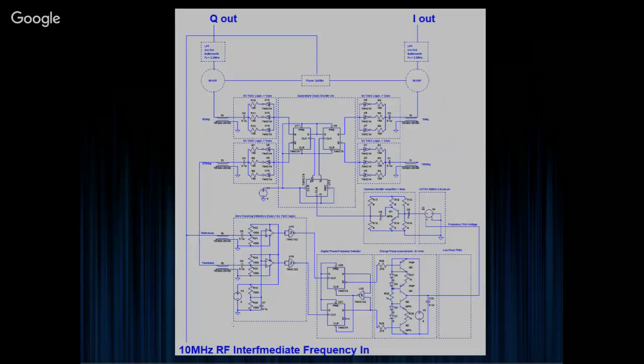to, well, actually, let's start from the carrier reference. So you've got a 10 megahertz reference. It comes in on the left-hand side. That's fed in as a reference to the phase-lock loop. So you can't adjust that, right? That becomes the reference. What you can adjust is your own oscillators. Then it gets taken around the top and fed into a power splitter. That power splitter, it's not very good. It's a 6 dB resistive splitter for wideband use, but then that gets fed in as the RF path on both mixers. So there's a mixer on the left and a mixer on the right.